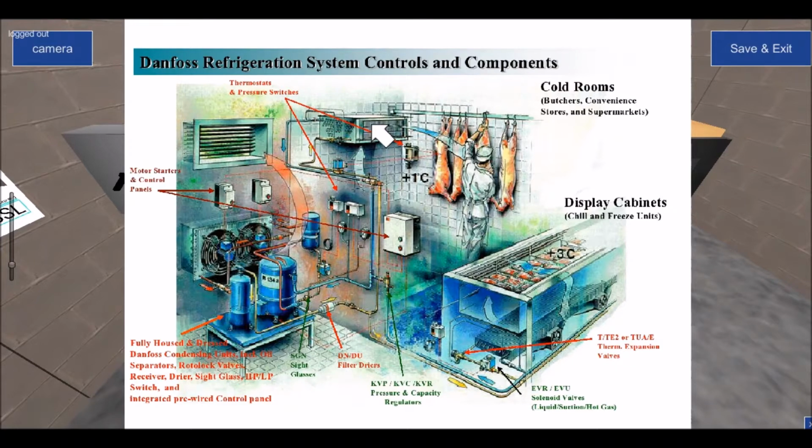The compressor pulls the remaining refrigerant that was in the evaporator out via the suction pipe all the way back, and discharges it into the high side of the system, back into the liquid line and up as far as the solenoid again. But because the solenoid is closed, no more refrigerant can enter the evaporator. So the evaporator eventually runs out of refrigerant, and when there's no more refrigerant in the evaporator, the pressure on the low side of the compressor drops down to 0, and the pressure switch, which you can see fitted here,